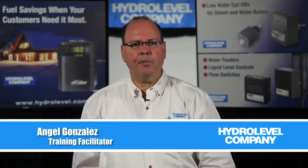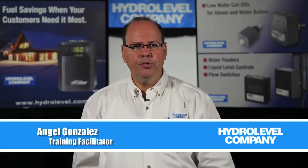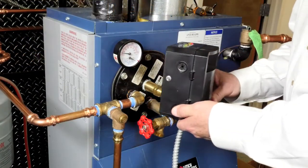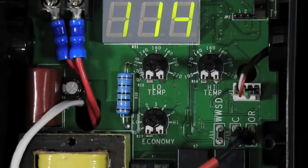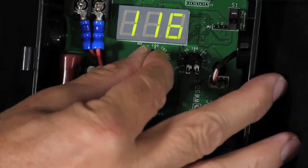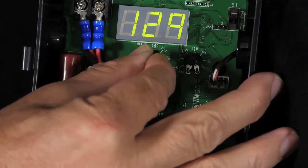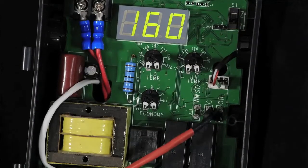Now let's look at the settings. The HydroStat operates much like an older aquastat control. So if you're using a HydroStat on a boiler equipped with a tankless coil for heating domestic hot water, you will want to maintain a low limit temperature to keep the coil hot at all times. To do so, simply turn the low limit dial clockwise until the desired temperature is displayed. For proper operation, the low temperature setting should be at least 10 degrees below the high limit setting.